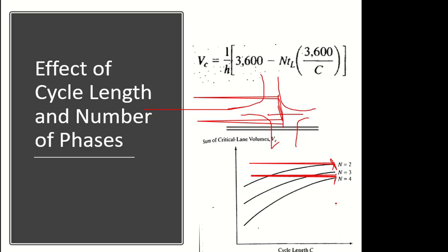So if the signal became red, cycle length is the time you have to wait till the next red. Or cycle length is the time during which other directions are having green, right? So when you go from one red to another red, your waiting time is increasing. If your cycle length is increasing, your waiting time is increasing as well.